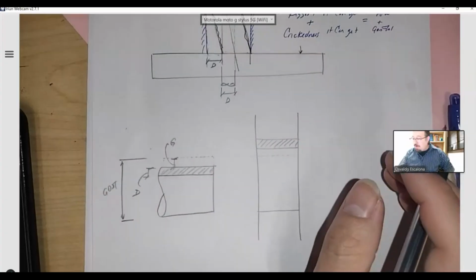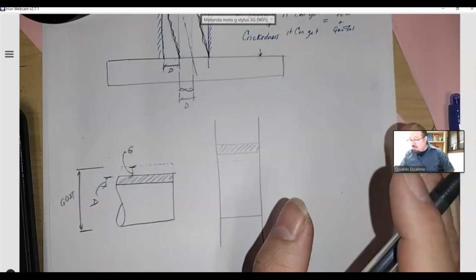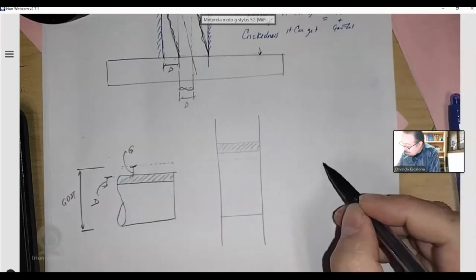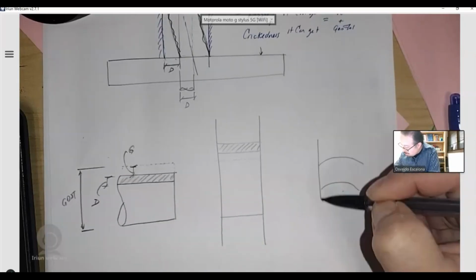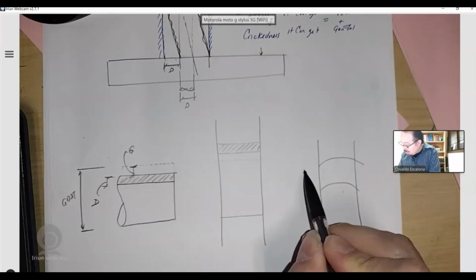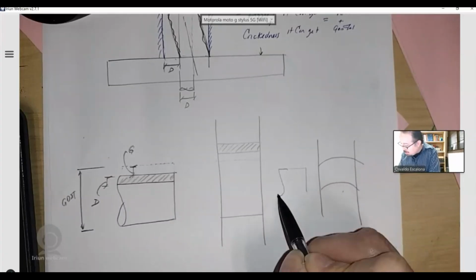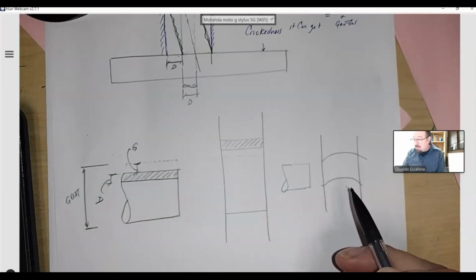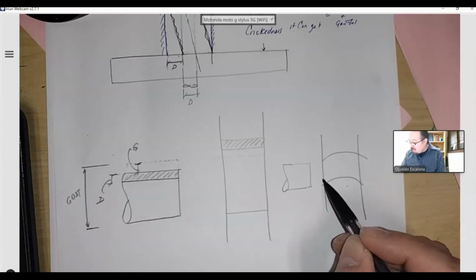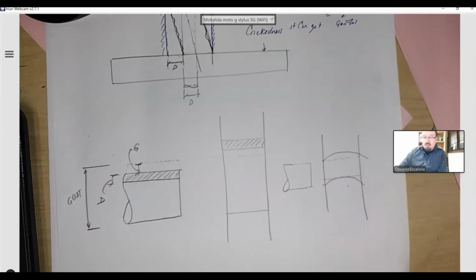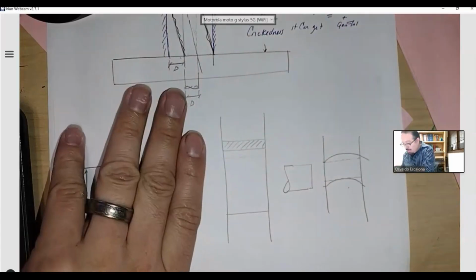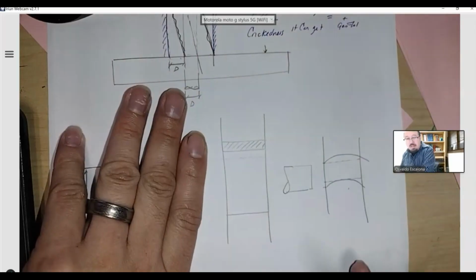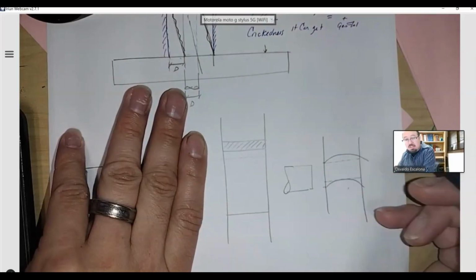Now, in the problem of the hole, it's a little bit different though, because when I have a hole, and if I were to put a hole like this, let's say I make a hole that is crooked, like that, and I want to put a pin that is perfectly straight, right? And I try to put a pin inside of the hole, it will not fit. And why doesn't it fit? It's because any type of crookedness that goes into the hole will actually generate a smaller hole, right? So how do I account for this? Well, I need to ensure that my hole gets decreased by the size of the geometric imperfection.